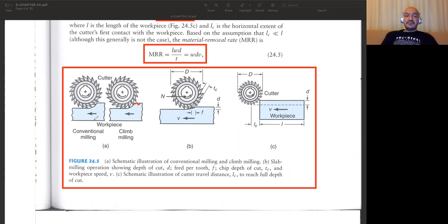But on the other hand, if you look at conventional milling case, we are actually in contact with the machined surface. So since it's machined, we can assume that that surface is much more clear than the surface actually we are facing in the climb milling. So I can say that you can use the milling cutter in the conventional milling more than the milling cutters you are using in the climb milling. So the tool life is much different in these two different types of operation.